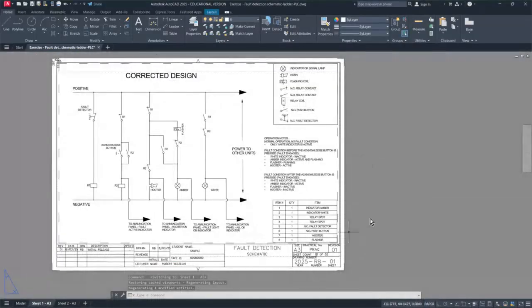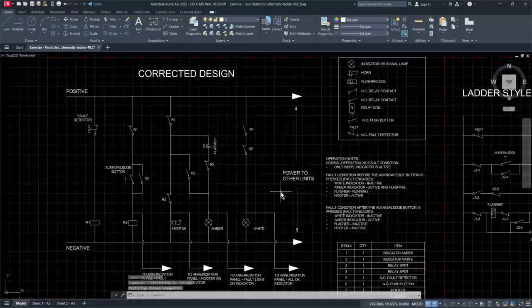Okay. Now, when you do things, make sure that every drawing is in the drawing frame, that you've got your legend, operational notes, how the system operates. I've also included the item quantity and the names of the items. It's a partial BOM. You can create a more comprehensive BOM if you want. You can actually indicate what type of relay stack. Okay, this is SPDT, but how many contacts, and some extra information. So this is the place to put extra information.